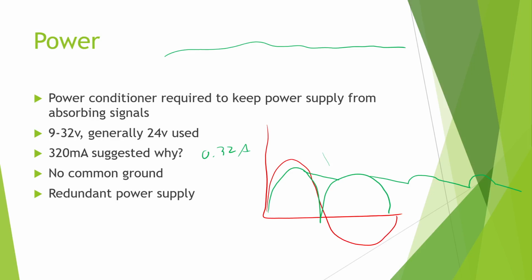We want to avoid having a common ground, and that is to help reduce the noise from other equipment. Now, common ground is not the negative on the battery. Very often, you'll hear me and probably other people say negative and common, ground, same thing, right? You're like, oh, you connect that to ground. Negative and ground are technically not the same thing, so we need to make sure we keep those separate in the long run. I have a hard time with this myself. I know I screw it up. Anytime I talk about the world DC, it's like, yeah, that's the ground connection. It's like negative. I don't know why I've just gotten ground stuck in my head, something I really need to fix.